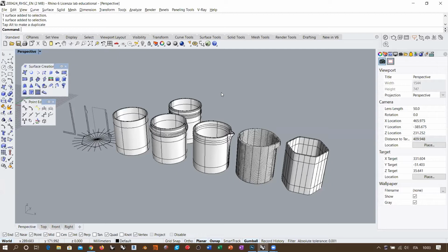Consider that in this case we are considering a particular degree 2 continuous curve, which is the circle. The circle is a particular curve because it has some full multiplicity knots along the path, at the quadrants. In that case, you have kink points.